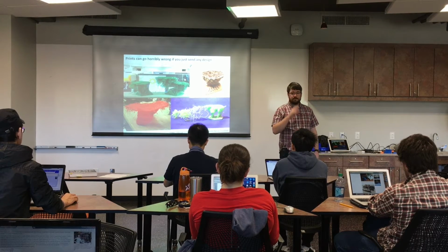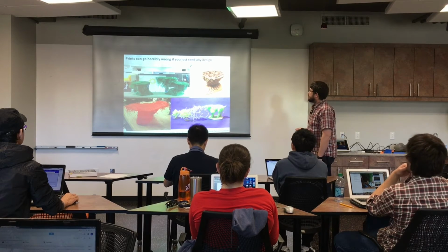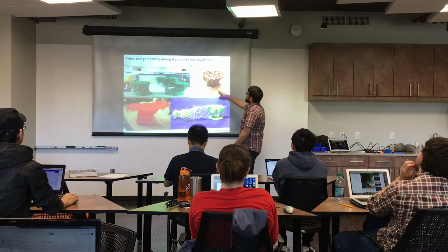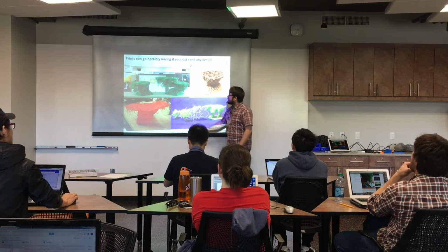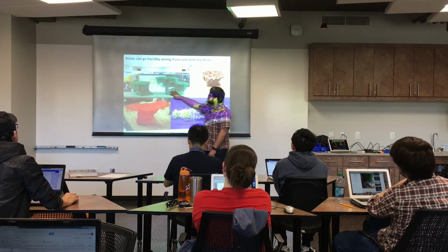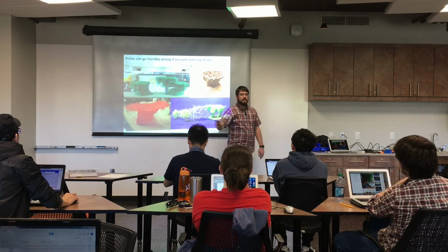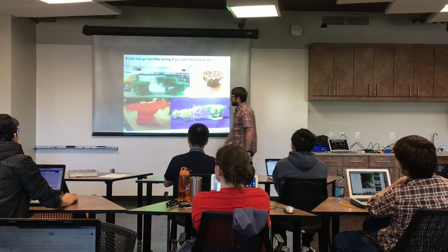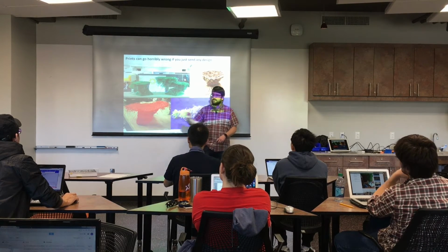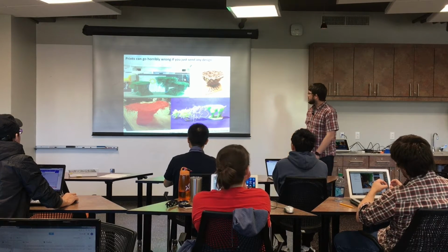So these are some examples of prints gone wrong. I was telling you that things can go wrong very quickly. For example, here something happened partway through and I guess they stopped it. This is a problem with a shift where somehow the printer coordinate system got shifted. This was supposed to be Walt Disney, and it's clearly not. You can start dragging the print head and mushrooming out the top of the print because something didn't secure well.